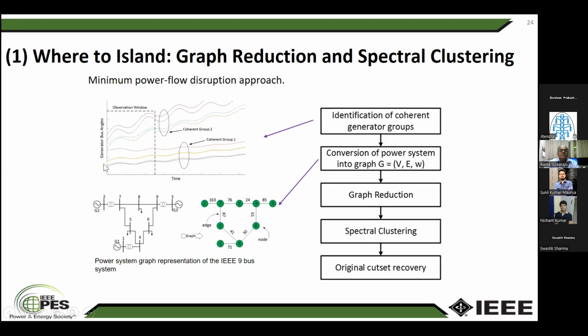Okay. So these things, they are all following similar patterns. This is one coherent group, and these generators out here. These two swings, they are together, and these two swings, but the pattern, if you see, they are going together. They may further split later on, but for the initial split, it is two groups here. So coherent group 1 here, coherent group 2.